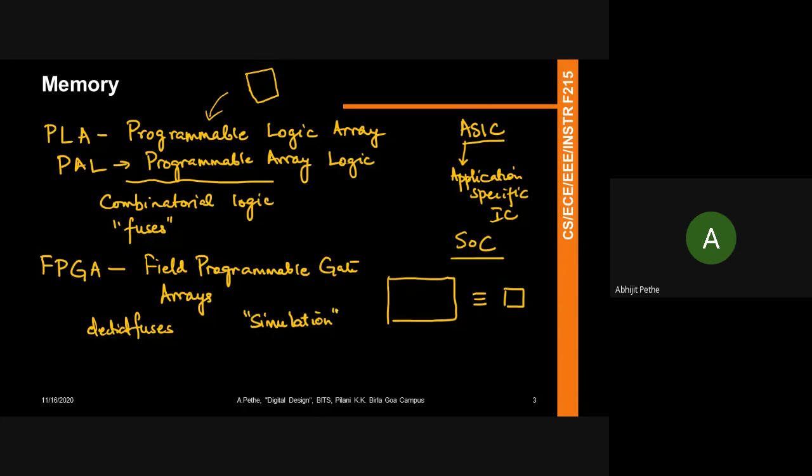Eventually an FPGA works out to be a very expensive solution, because an FPGA is a very expensive chip. It's a large chip, it's a power hungry chip. So you cannot design a product on an FPGA. But what you can do is take the FPGA, test your design on it, confirm your field level analysis, and then come back and do the same thing on the SoC. By learning from the field, you can implement a better SoC.